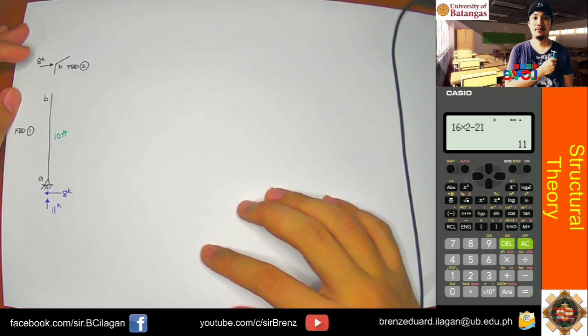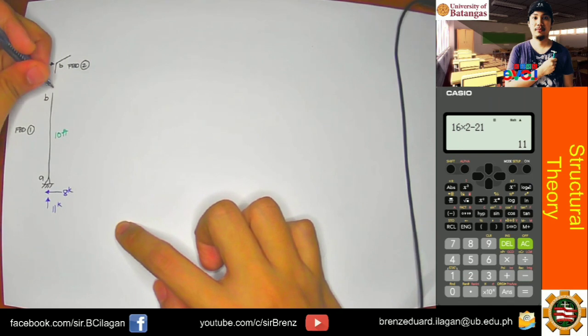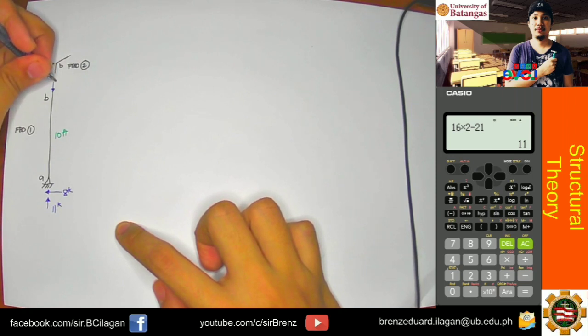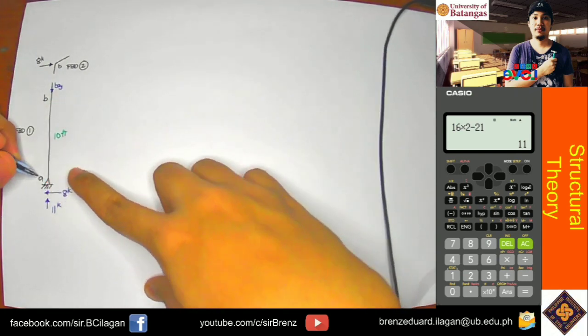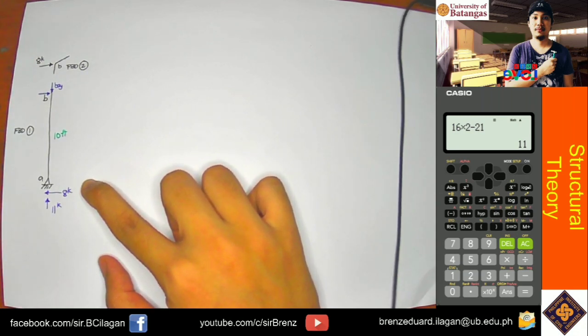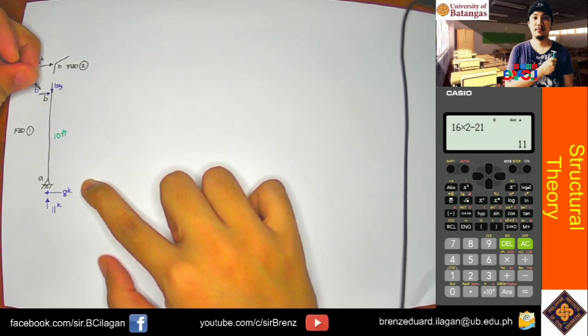So unahin muna natin, hanapin natin yung mga internal force acting in this column. Okay, so by analysis alone, I could say na ito ay pababa. So let's name this as my BAY, since yung member na ino-consider natin is from B to A. The next, yung BAX ko, so sabihin ko na pa ganito siya. Since yung force mo is 8 kips, which is going to the left, so dapat ito to the right. So this will be my BAX.